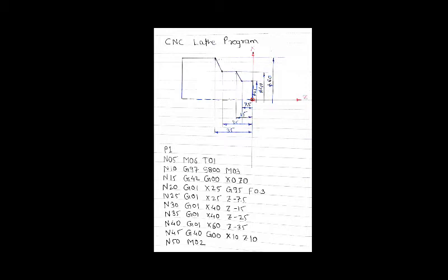With such programming, an error is caused by the tool rounding. The actual shape of the tool's nose is round, but we treat it as a point. So the error occurs during taper turning or arc interpolation between the actual program shape and the cutting shape.